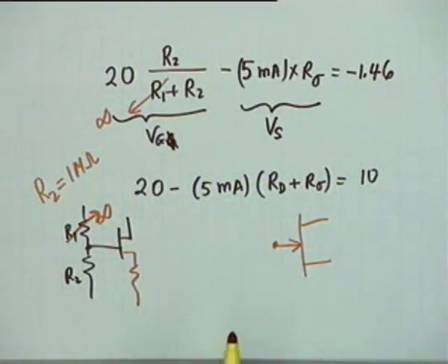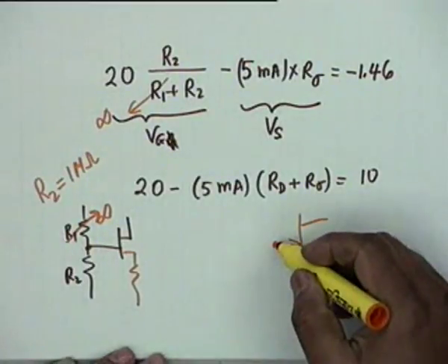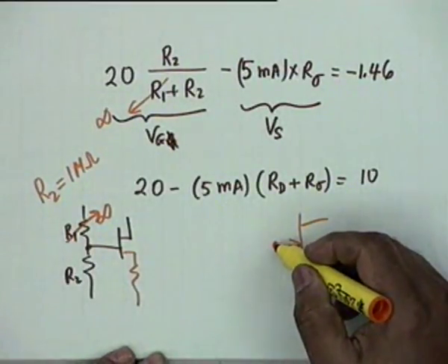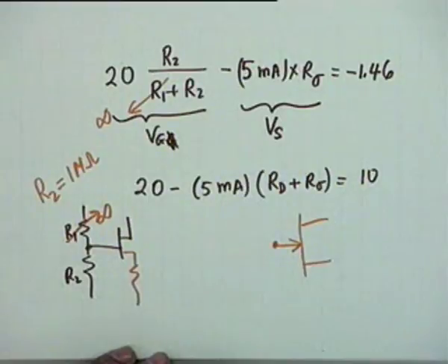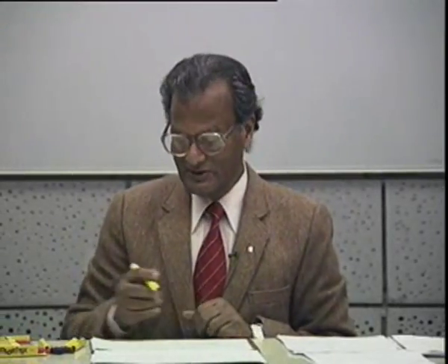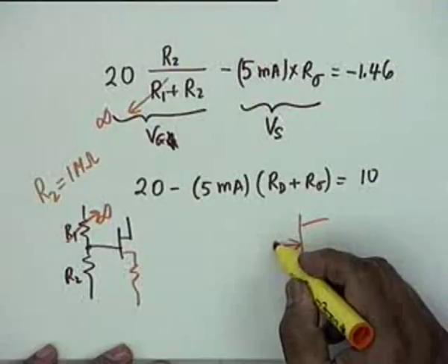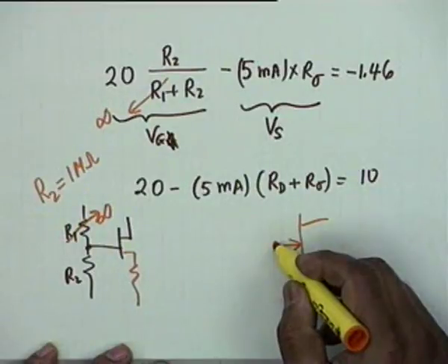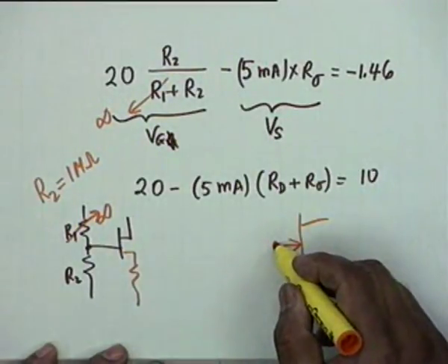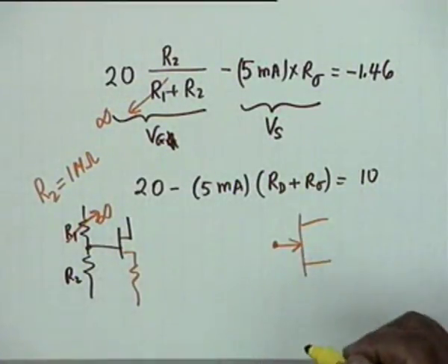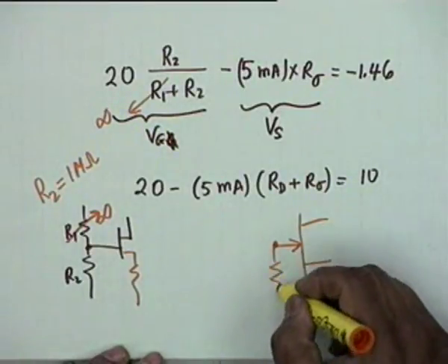Suppose it's a very dry atmosphere, then there is static charge in the atmosphere. It accumulates charge, and VGS may be such that the operation goes into a different region. Also, then VGS will not be controlled. So what we want is, we must provide a path for any charge that tends to accumulate to go to ground. That's why we must use a resistance.